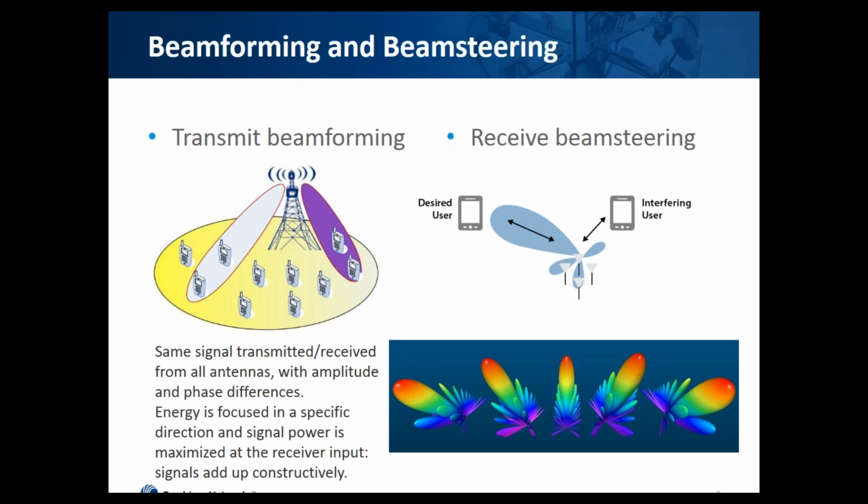For this method to be effective, we need to know where the receiver is, or alternatively, what the channel looks like. Assume a point-to-multipoint scenario, where one access point talks to multiple devices. The access point has the channel state information for each device. When talking to device 1, it will use the channel information for device 1 and point the beam towards that device. Then, if it needs to send data to device 2, it will use the channel information for device 2 and point the beam towards device 2, and so on.